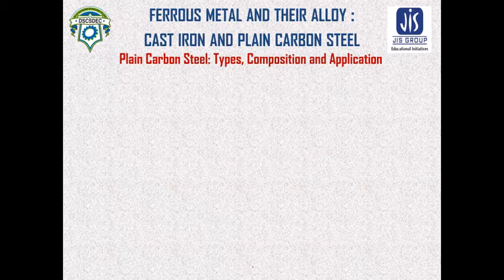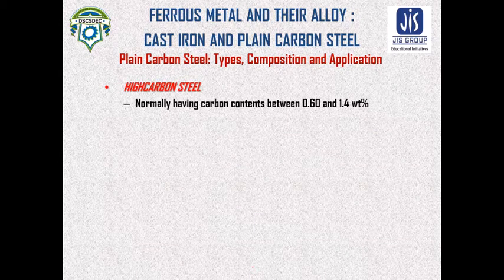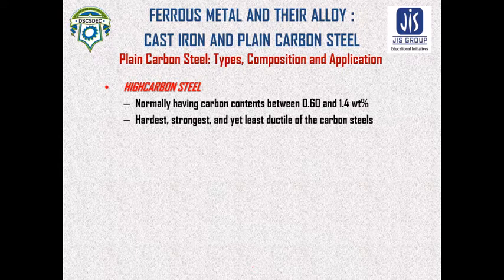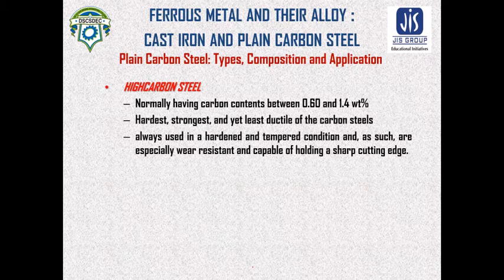Now for high carbon steel, the carbon content is normally between 0.6 and 1.4 weight percent. It is the hardest, strongest, and yet least ductile of the carbon steels. It is always used in a hardened and tempered condition.